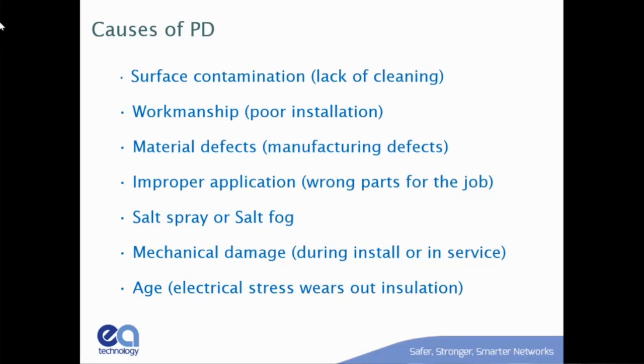But there are lots of causes. Surface contamination: if you don't clean your insulators, you don't clean your switchgear. I think there's a picture later on where somebody in Florida, out in the swamps, had an engine test stand with horizontal surfaces between the bus bar, and they didn't go in and clean it. So they got contamination. The contamination attracted moisture. Moisture changed the field stresses and led to discharge. So cleaning your gear is going to help.